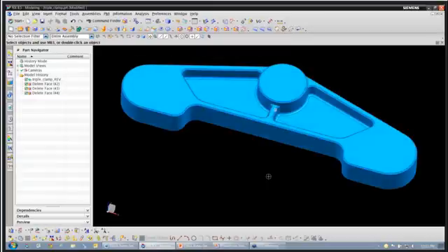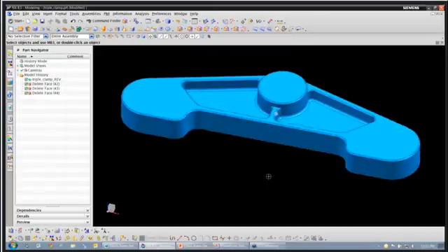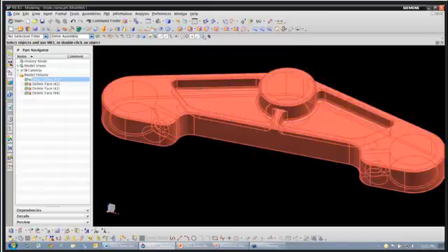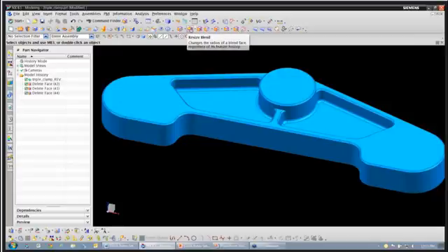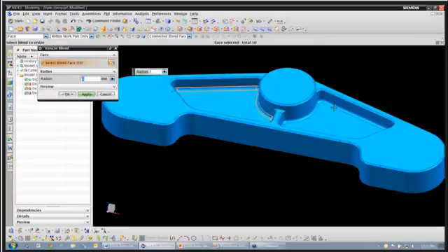All right, and another thing I want to do is resize these blends down here in the bottom of this pocket. So I'll just use the resize blend. Just tell them that these are an R2. I'm going to change those to an R6.